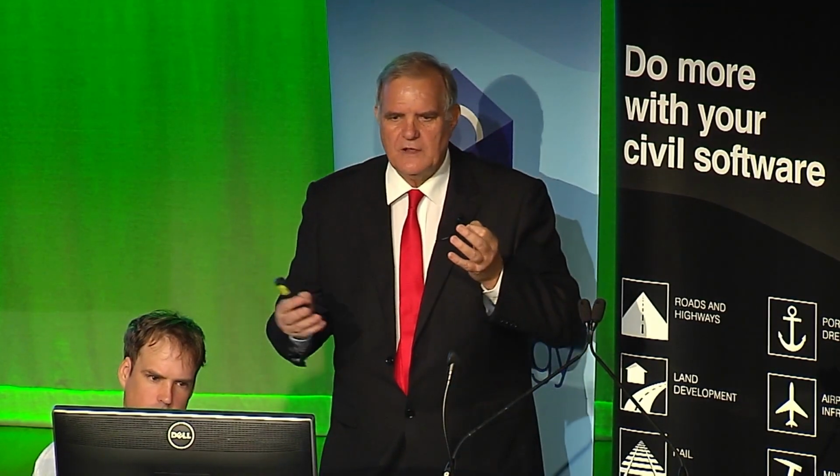So it means if you're trying to pick something in a perspective view and it's a trimesh, and you click on it, you'll get an XYZ value from that trimesh. So you can just join things up there quite happily. And similarly with those trimeshes, you can turn face snap off, and if you've got point snap on, it'll grab the vertices of the trimesh. If you've got line snap turned on, it'll get an edge of the trimesh. So this will allow you to get the vertex, edge, or right onto a face of a trimesh.